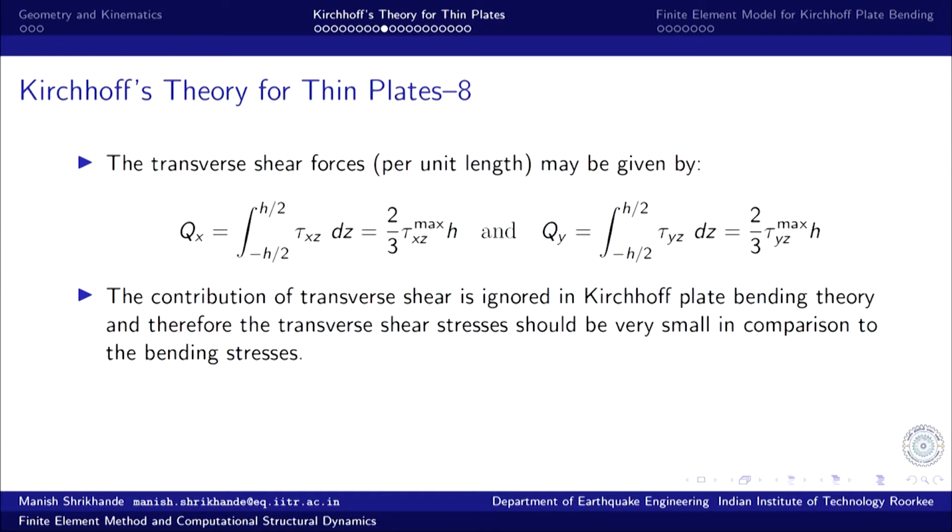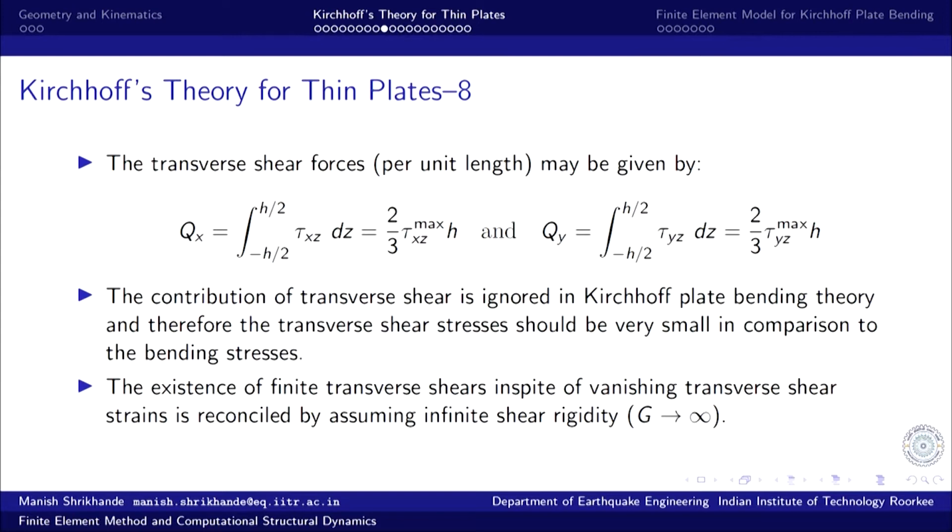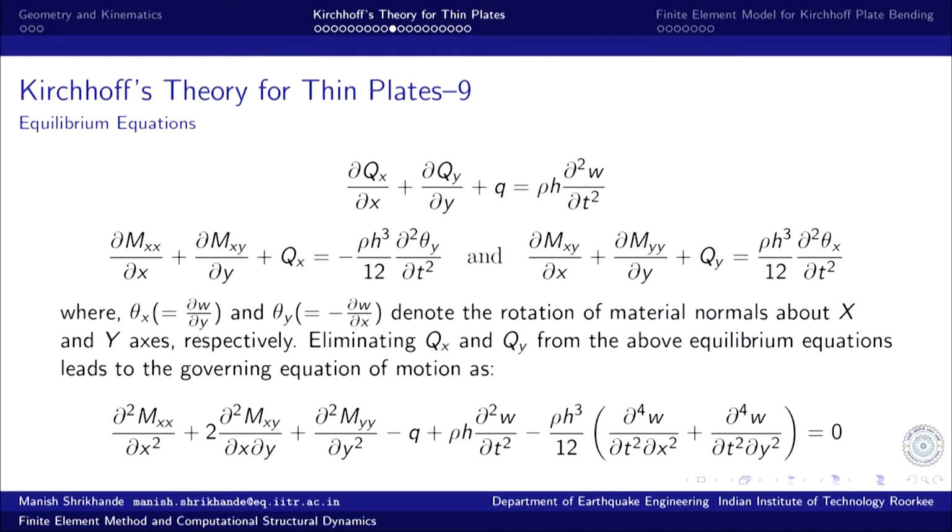So, the contribution of transverse shear is ignored in Kirchhoff plate bending theory, and therefore transverse shear stresses should be very small in comparison with the bending stresses that actually govern the behavior. The existence of finite transverse shears in spite of vanishing transverse shear strain is reconciled by assuming infinite shear rigidity, as I mentioned earlier.